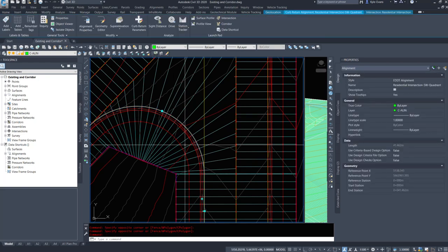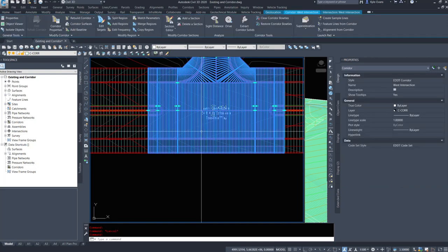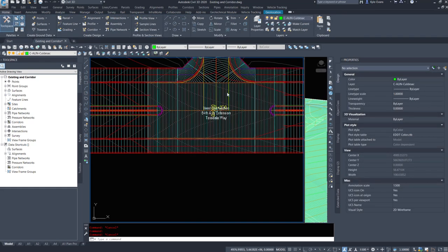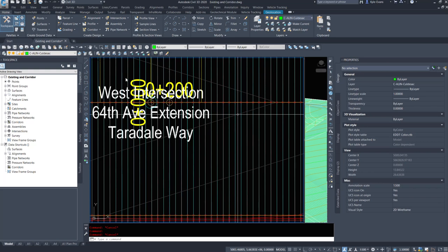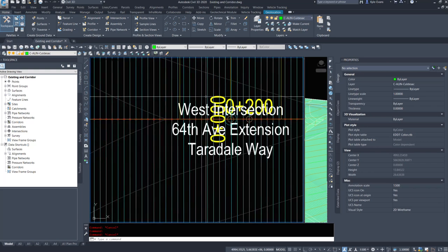One of the problems with the intersections is if we build an intersection and it's wrong and we end up deleting it, so I delete this and I think I'm good, the 6 alignments stay in your drawing. The intersection marker itself stays in your drawing, so you're going to end up having additional intersections, additional alignments.